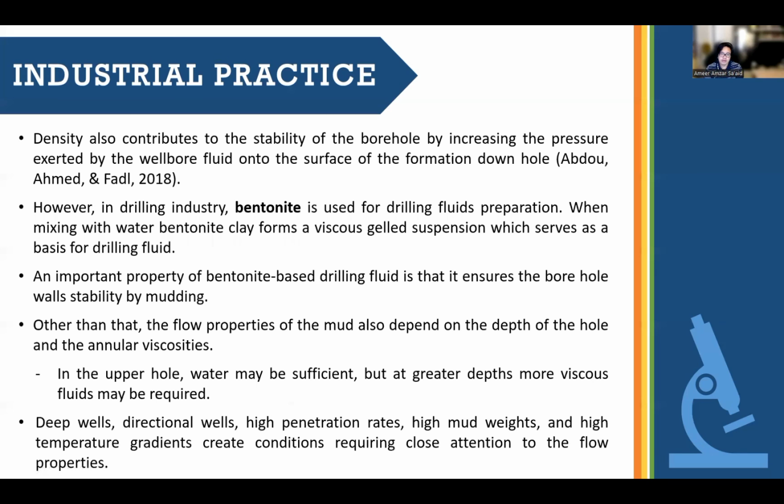The next point is that density also contributes to the stability of the borehole by increasing the pressure exerted by the wellbore fluid onto the surface of the formation downhole. However, in the drilling industry, bentonite is used for drilling fluid preparation. When mixed with water, bentonite forms a viscous gel suspension which serves as a basis for drilling fluid.